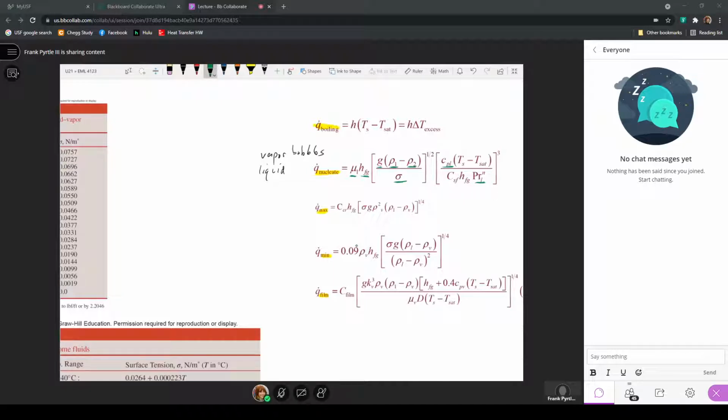And then we have this constant here, C sub SF, and it's just a constant associated with the particular surface on which boiling is actually occurring. It's an experimental constant that depends on the surface-liquid combination. And there's a value n on the Prandtl number. It's another experimental constant that depends on the fluid. So when we're considering calculation of a heat flux in the nucleate pool boiling range, this is the expression that we would use.